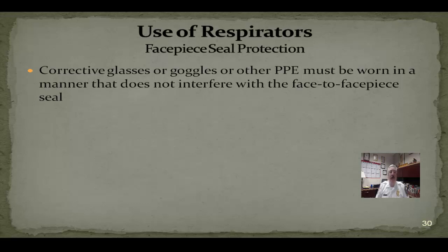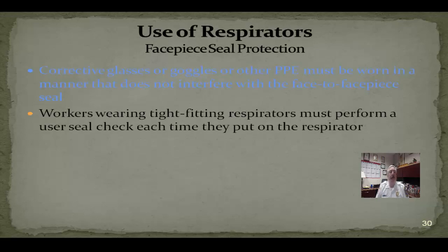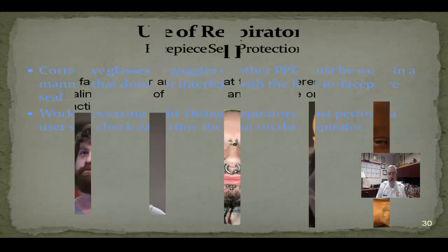If you wear glasses and you're wearing a full-face SCBA or full-face respirator, we will provide adapters that you can get your lenses fitted to and actually put on the inside with you. But they should not interfere with the face-to-face piece seal. Anytime that you don a tight-fitting respirator, you must perform a seal check each and every time.